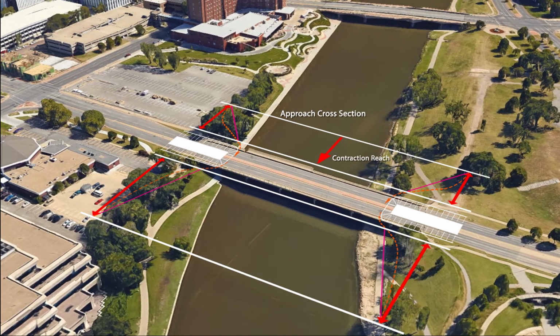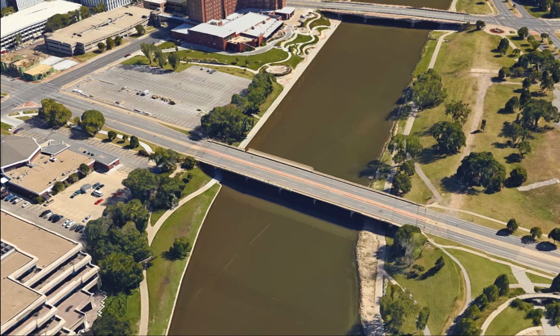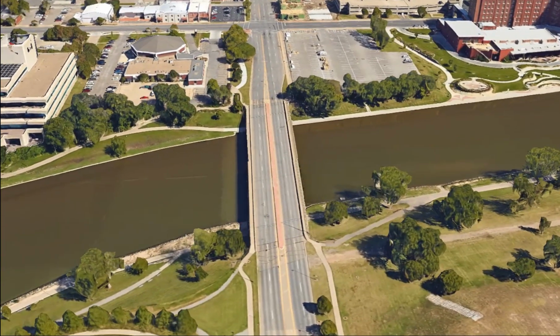The distance that the approach cross-section is offset upstream from the upstream face cross-section can vary based upon the geometry of the river overbank, the speed at which the river flows, and other site-specific conditions. However, a rule of thumb you can use is that the flow contracts at a 1:1 to a 2:1 ratio. So if the overbank flow on one side of the river needs to contract 100 feet inward to get through the bridge opening, you will want to place the approach cross-section at a distance between 100 to 200 feet upstream of the upstream face cross-section. Again, this is a rule of thumb and is subject to change based upon the local conditions being modeled.